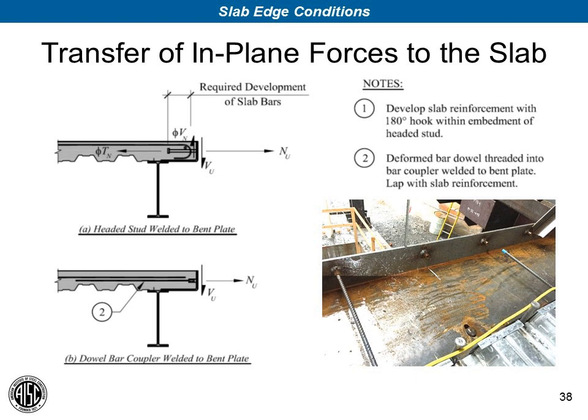So provided that you're not relying on a slip critical connection between the bent plate and the beam flange, you can actually use a very long slotted hole here for erection. I've specified as much as a 3-inch long slot to allow for a great deal of adjustability. The condition you see in the photograph is in fact not a spandrel beam. It's at an elevator opening. But the concept is the same. You want to provide lots of adjustability in the field, and then when the final location is established, this gets field welded and the erection fastener isn't doing anything at that point. So I usually specify a slot even longer than a long slotted hole.